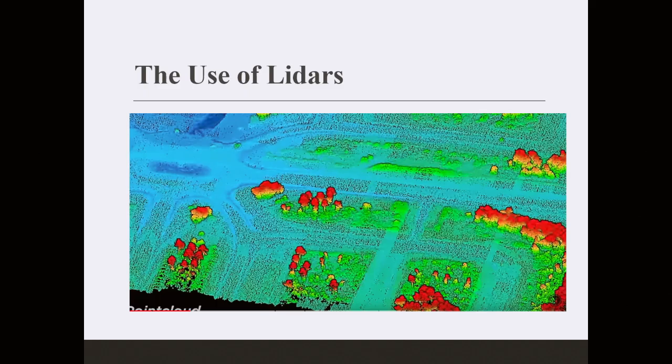AI can translate this raw data into a crack or raveling or a pothole or rut, etc. So by the end of the day, you can have a scan of 500-600 kilometers worth of a road network, done by one person driving one car at almost the same regular speed as other traffic. So you're not impeding traffic. It's 100% accurate. It is the start point of data collection.